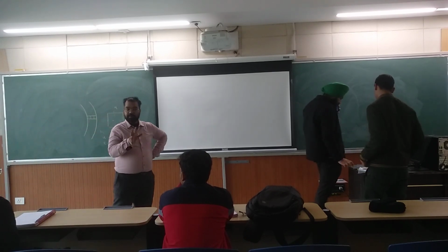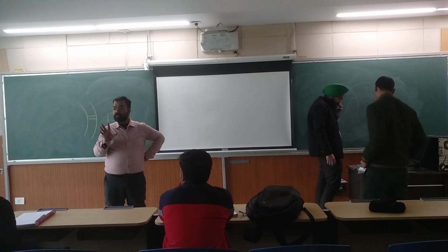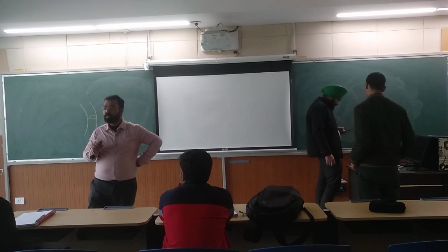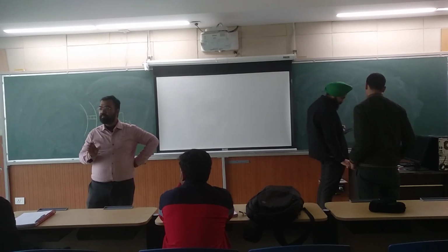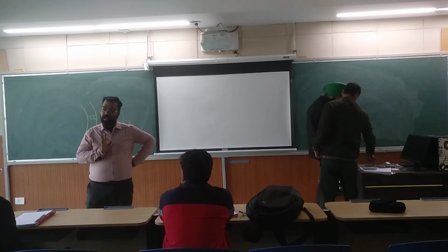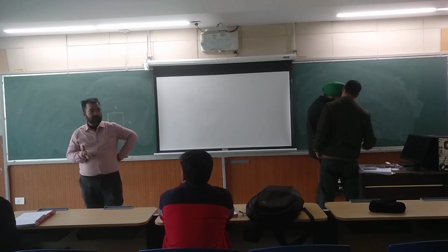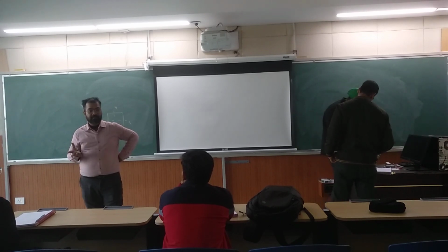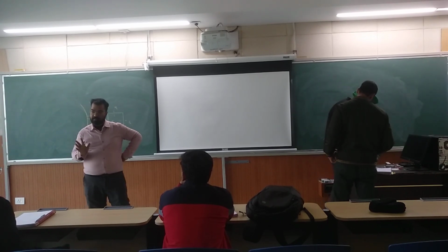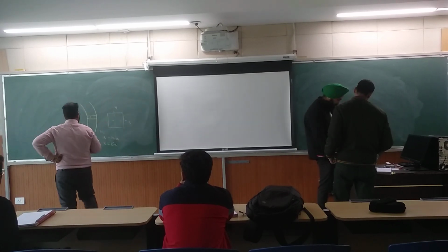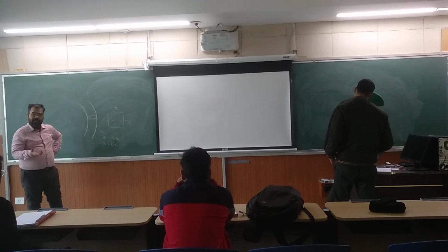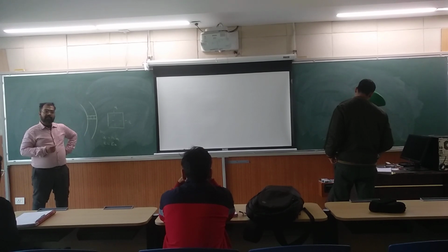Okay? So what are we trying to do? We are trying to find out a numerical algorithm, a numerical technique by which we can calculate complicated things by dividing into small pieces where simple calculation can be done. And if we increase these numbers of simple calculations, we can also approximate a very complicated function. Do you follow? Okay? So we will do all those things. So u and epsilon and stress, and from stress we will calculate a stiffness matrix, and then we will do what?